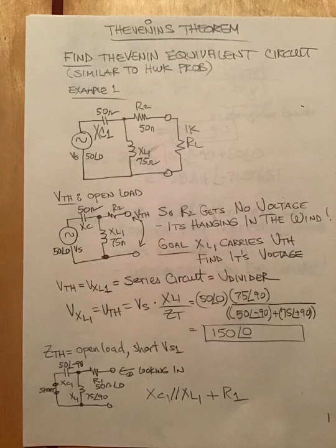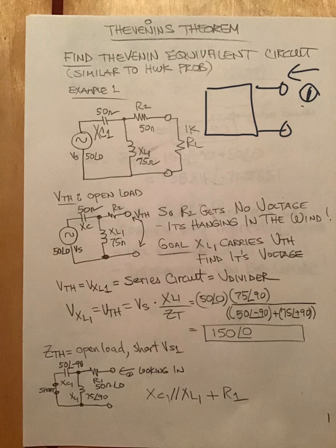Okay, and you look into the Thevenin circuit there, and you see one of those circuits that I warned you about, that you've got two terminals out there, your eyeball is looking in, and you've either got a parallel resistor there or you've got a series resistor, and there's somebody behind that series resistor. Do you see the black circle? There's somebody behind the resistor. Now that's just an inductor, but there could have been two inductors. There could have been a resistor and an inductor in that path. We keep it simple and we usually leave just one component.